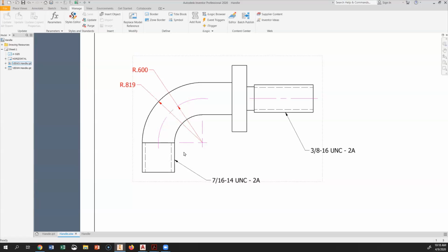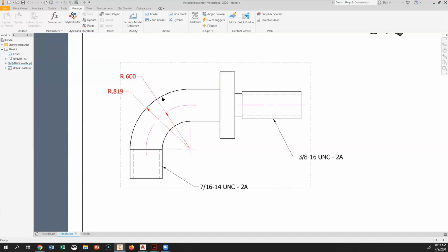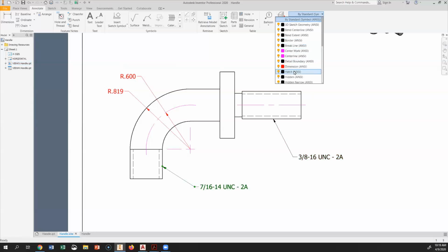And because you have these dimensions that require 3/8 and other things. Okay. These two stay black. Remember the reason for that? Because they don't belong to the same layer. So what we do usually, go to annotate, select these two, or you have to select one at a time, and then change to dimension.